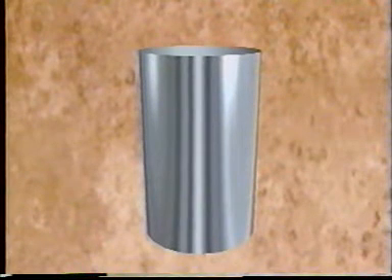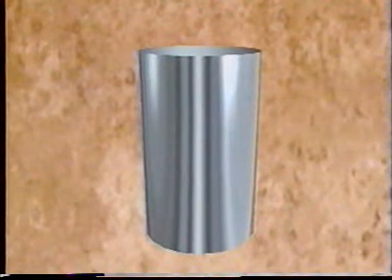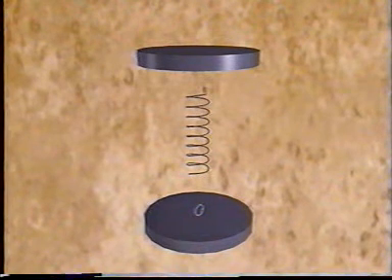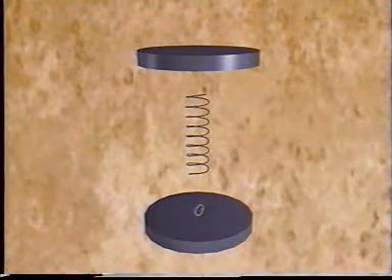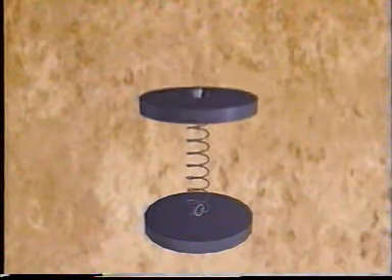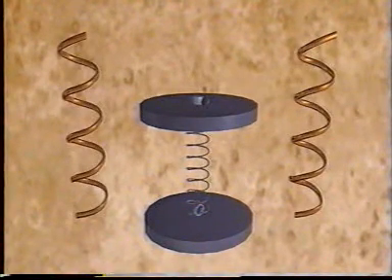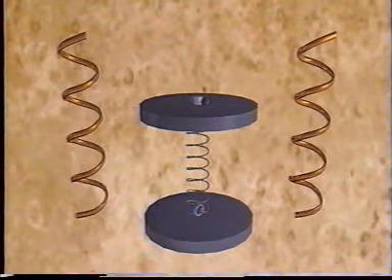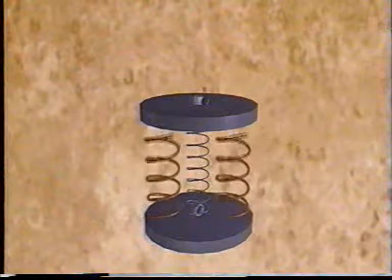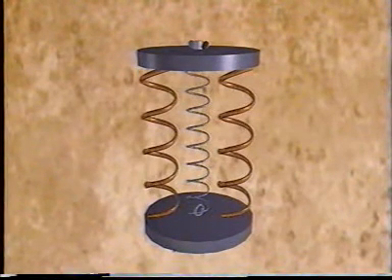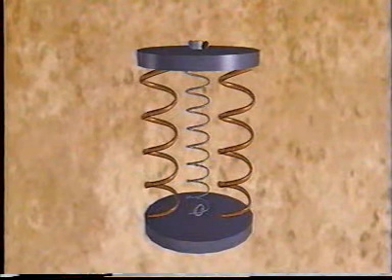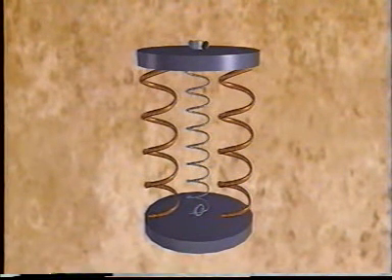To help visualize the residual stresses within a metal part or assembly of parts, we can think of them as springs. A tension spring can represent a tensile residual stress. When loaded in tension, the spring is stretched like a rubber band. A compression spring, representing a compressive residual stress, is compressed like a rubber pad. In this particular model, with the two types of springs between two blocks, a balanced, stable stress system can be created by adding another compressive spring.